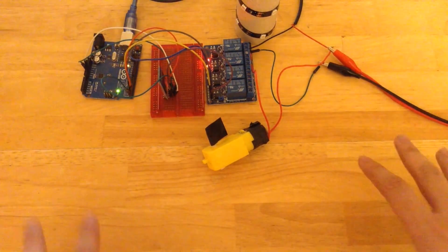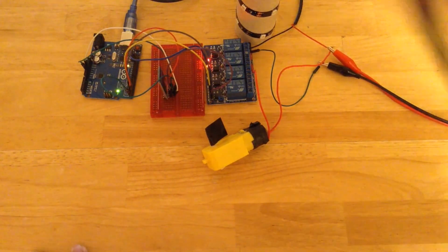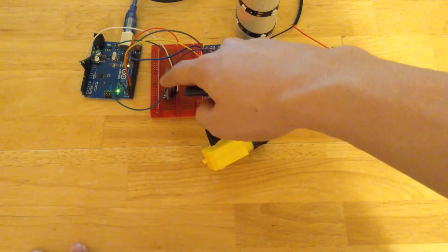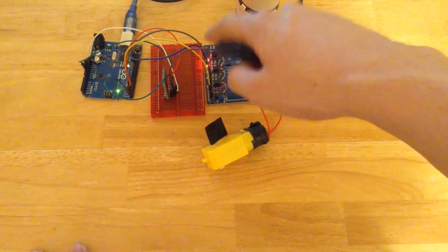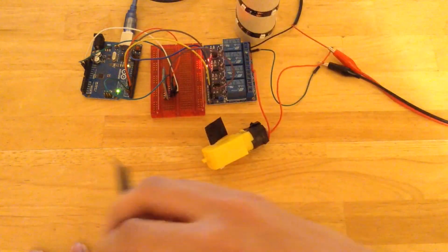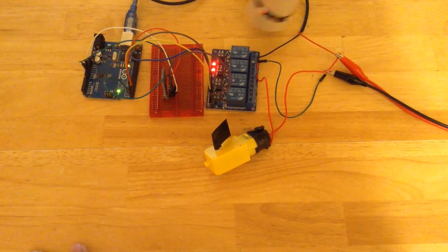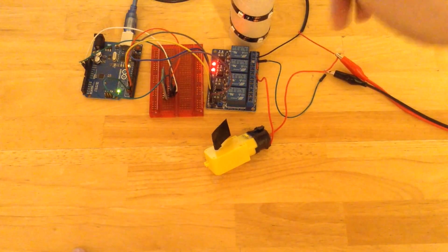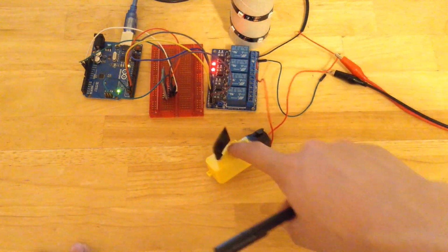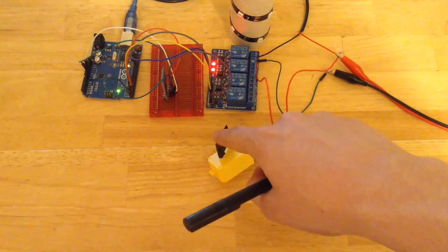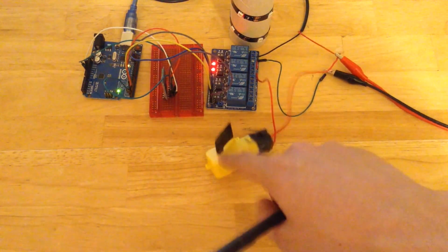Okay, so here I have the Arduino and all the circuitry set up. I got the Arduino Uno hooked up to the HC-05 Bluetooth module. All of that's hooked up. Then my relay board is hooked up to pins 3 and 4 on the digital pins of the Arduino. Now the light, the toilet roll with the LEDs on, represents the lights on and off, and the motor is replacing the door lock. So when it's rotating, it's locked, and when it's not rotating, it's unlocked.